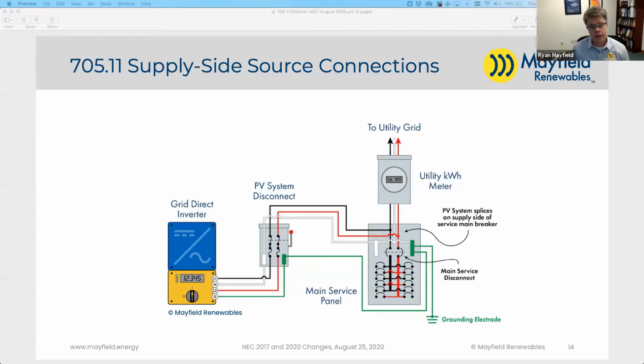Yeah, I've seen that too. And the one caveat with that is making sure that, with the inverter manufacturer, you're still properly protecting the inverter. I won't say most, but a number of inverters do have that ability, but it's a matter of their listing. So that is the quote unquote easy answer, as long as you're still properly protecting the inverter for sure.